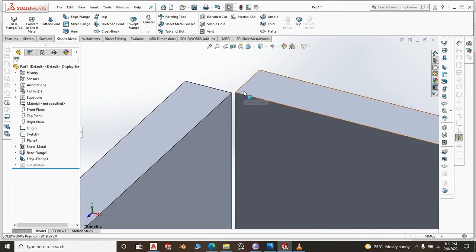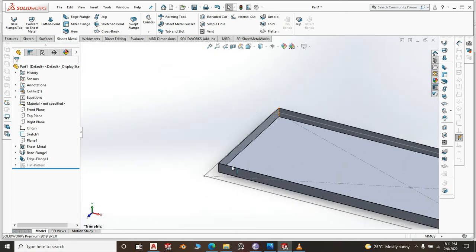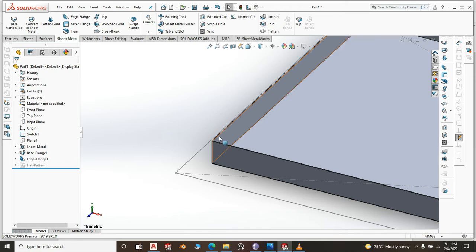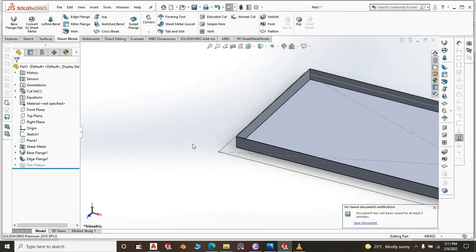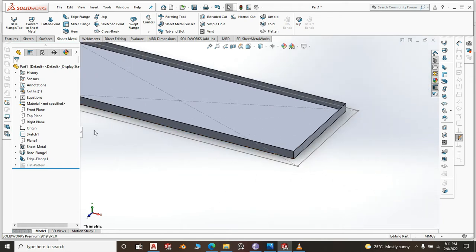It's just about 0.1 millimeter, which is okay, because the welding will be done from outside, not inside, and you don't want a lot of welding to penetrate on this other side, the face side. Polishing will be very hectic.